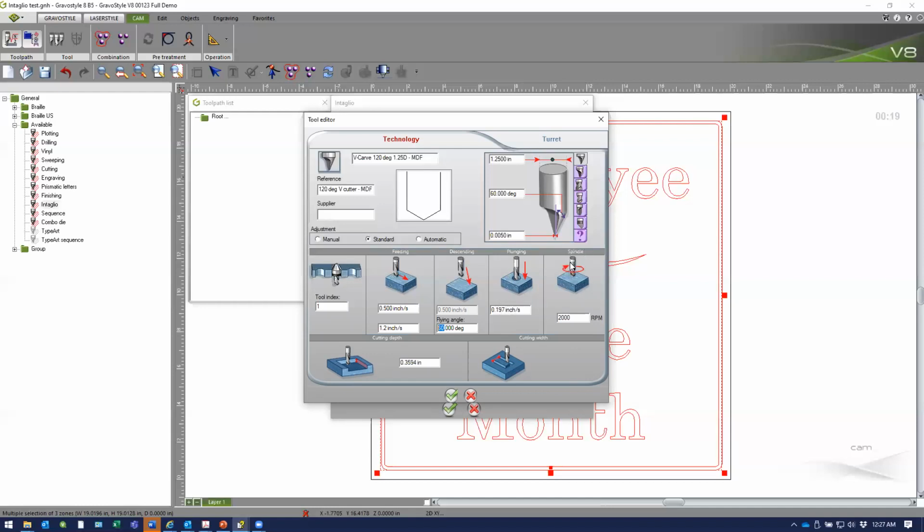Okay. And then the next is this rotation speed of the cutter. This only really applies to the milling machine that has the automatic tool changer, but oftentimes I'll put in here a reference to tell me that I typically want to rotate this cutter at about 18,000 RPMs.